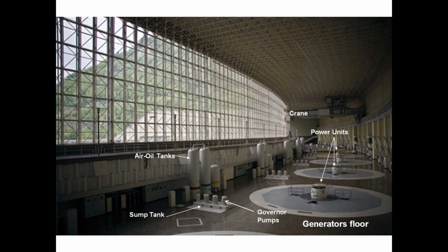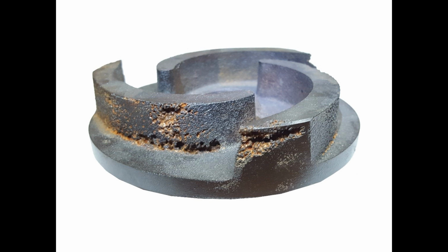And by boil, remember, what we mean is not that it's hot. It simply means that some of the liquid water molecules are turning into gaseous water molecules. It's vaporizing. So what you don't want is for the water to vaporize as it goes through this power plant. And the reason why you don't want it is that when the water vaporizes, remember that gases take up more space than liquids. If you boil water, it takes up more volume, and then when that bubble collapses, it sends a shock wave through the water.